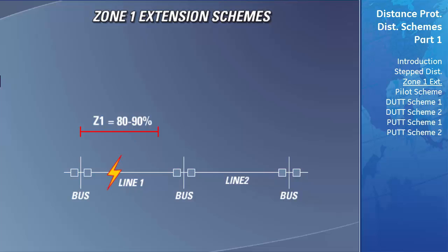If the fault that occurred was a permanent fault and located within the transmission line's newly shortened zone, the D60 will trip and again open the circuit breaker to clear the fault. If the fault was transient in nature, the first occurrence of tripping the line would have removed the fault and transmission of power would resume. If the fault was permanent and reappeared after the reclosing, but was not located in the new shortened Zone 1 protected area, the D60 would not pick this up for a second time in Zone 1 and not trip to try to clear the fault.